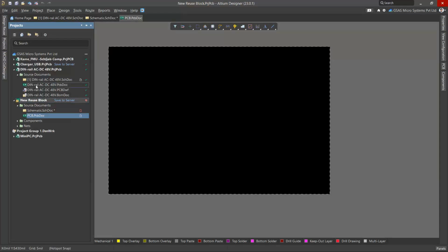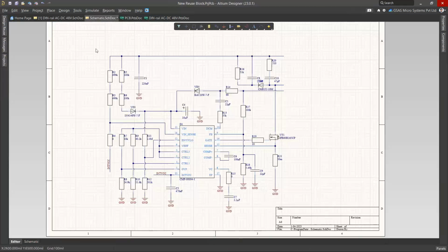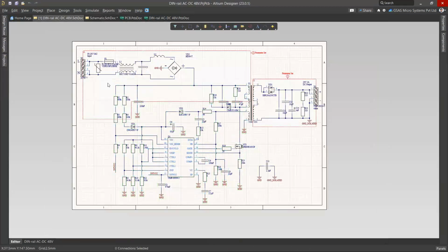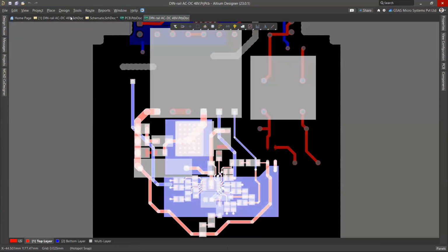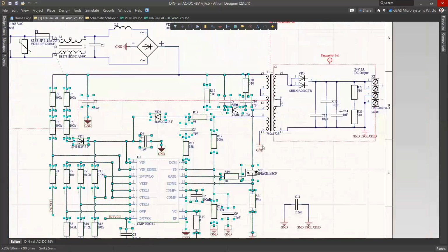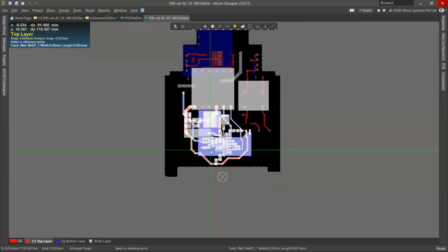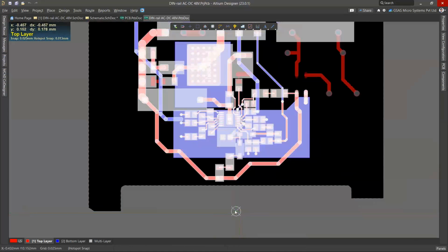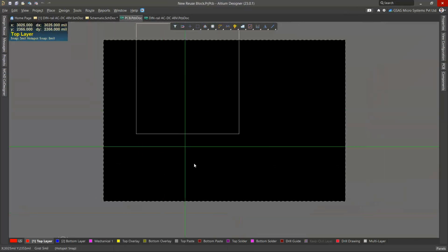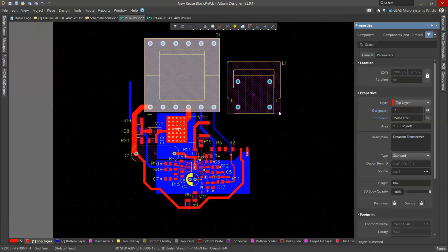Now let us open the PCB where you want to copy, and let us do the same selection again. So it will be getting copied. Yes, this is copied, and we don't want this section. I think yes, this is not copied. Yes, this is not copied. Now let us say copy and then go here and then paste. We don't want this component. Let us delete this.